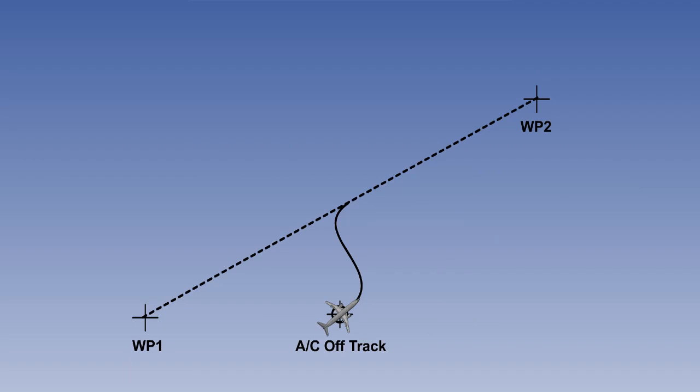The steer signal tracks the aircraft down the centre line of the route between the two waypoints in use. If the aircraft is out to the side of the route for any reason, it will be S-turned back onto the centre line at quite a sharp angle. It is not steered directly to the next waypoint.